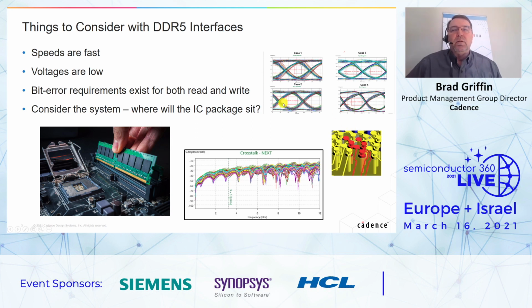And they also need to consider, obviously, from a signal integrity perspective, all the JEDEC requirements and all the various different mask requirements they have when you look at simulating multiple bits, or if you're in the lab with a prototype using a scope, capturing a long data run. You need to make sure that mask opening is meeting those requirements. And certainly we want to make sure from a simulation perspective that we're able to capture that way ahead of time, so we know what's going to happen when we go to the lab.